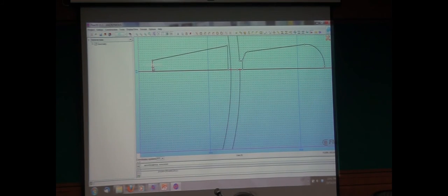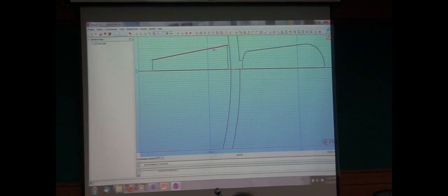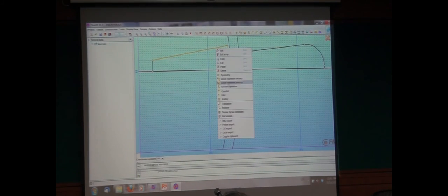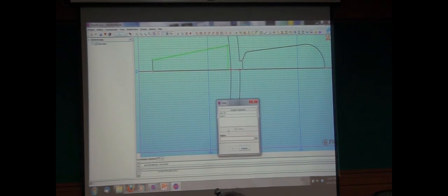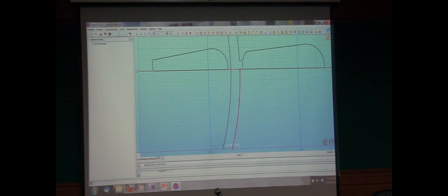And now to finish this, I'm going to create a fillet from here to here. Chamfer fillet. So, you can see as I try to fillet, right now it's probably telling me it's too big. Okay, that's 1. I can do 1.2 or 1.5, whatever. As I do stuff, I can see live my final geometry. I have an immediate preview. And I'm saying okay.